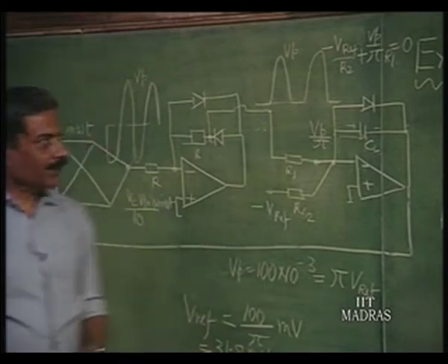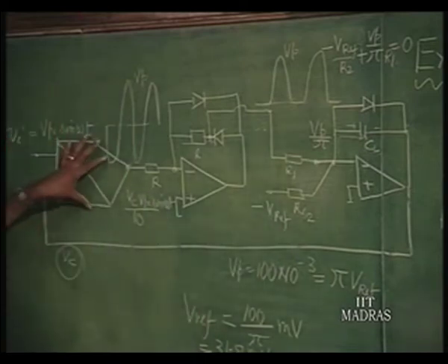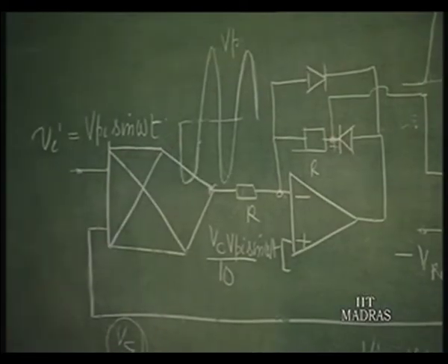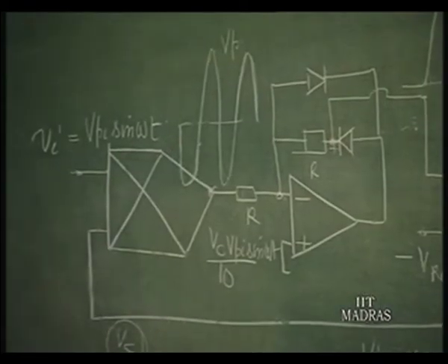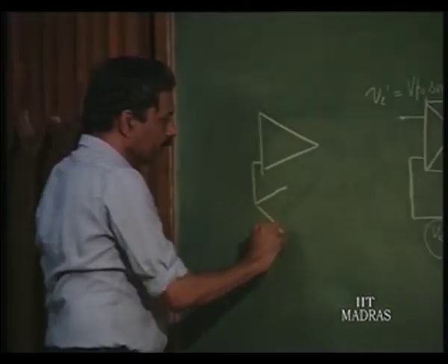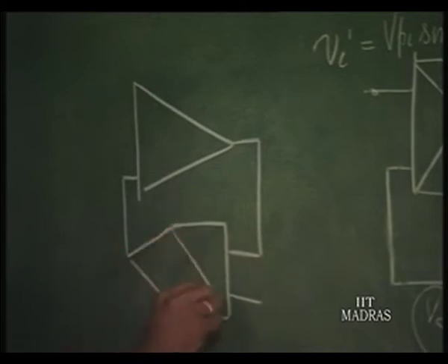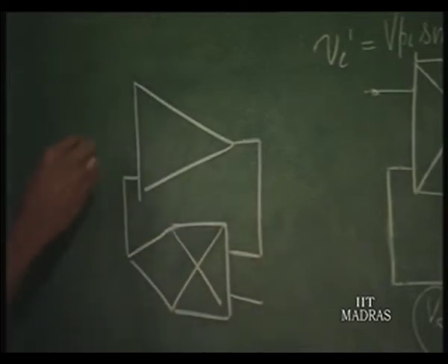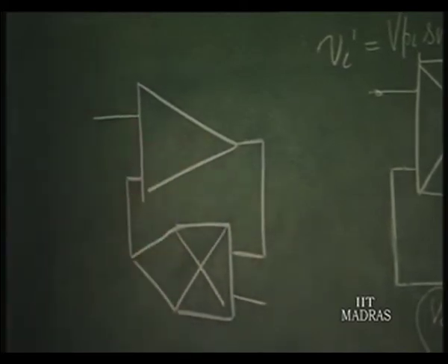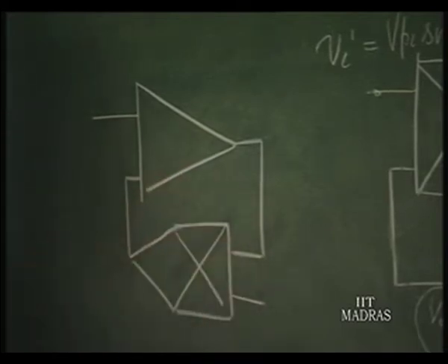Now, as far as oscillator is concerned, this can form part of the oscillator system like this. For example, a Wien bridge oscillator. So, instead of using a sort of resistive feedback, I can put a multiplier in the negative feedback, because its feedback factor is always less than 1. So, the multiplier is put in the feedback path of the non-inverting amplifier.